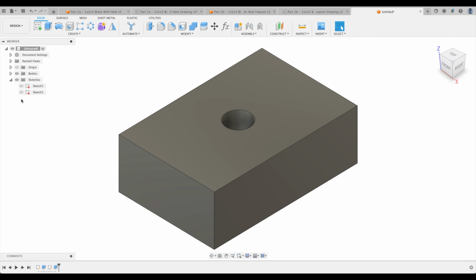So remember this, in Fusion, every time we extrude a sketch, Fusion is very smart and it assumes that we are done with that sketch. But in this instance, we're not. We'd like to bring it back and use it again. So let's unhide it. Now look at what we have. We have that small circle, the bigger circle, and we can even select our rectangular face here. So let's do another extrusion.